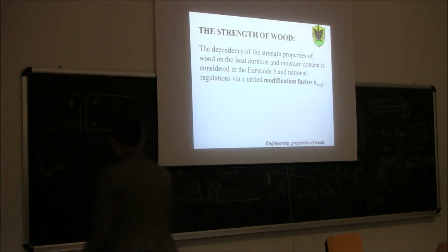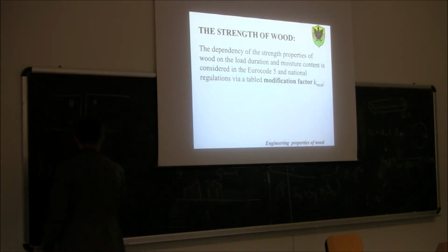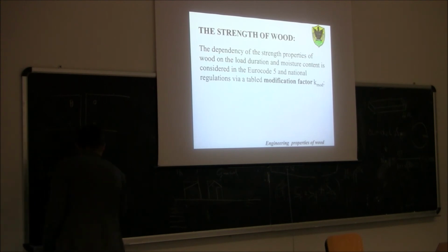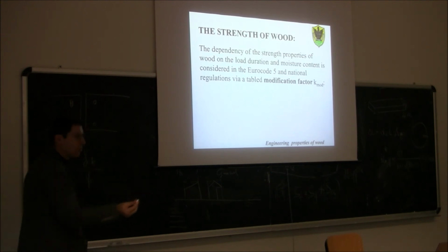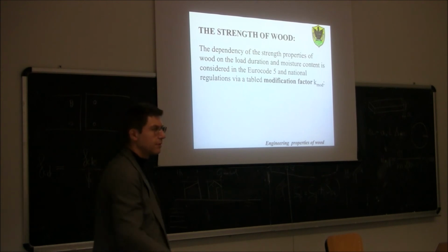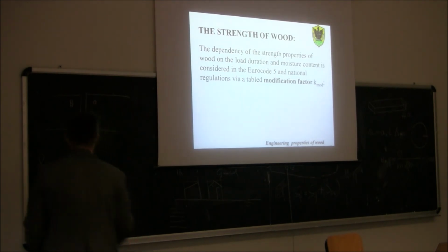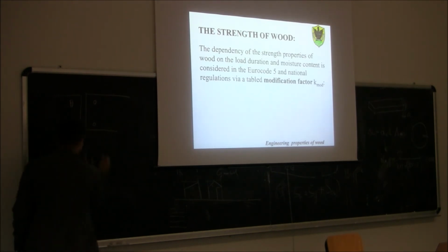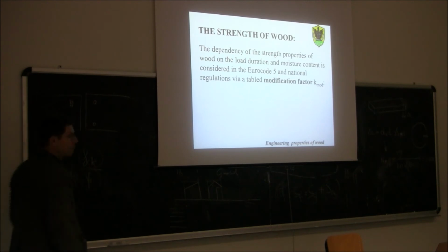the characteristic strength of concrete divided by the safety factor, gamma c, I don't remember now. Alpha cc, okay. So partial safety factor, characteristic value, what is alpha cc?